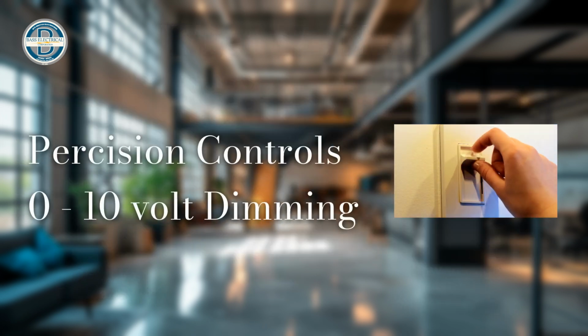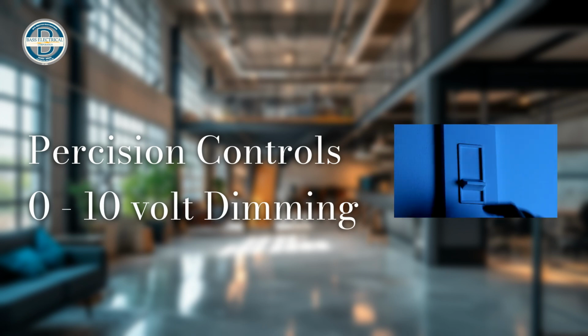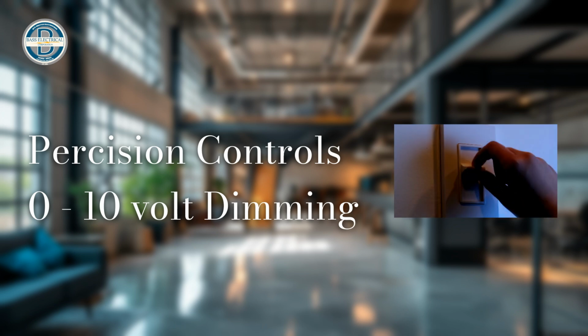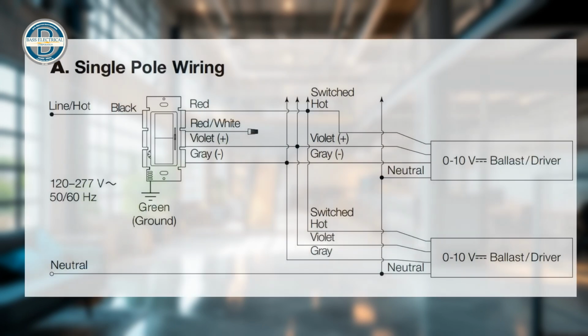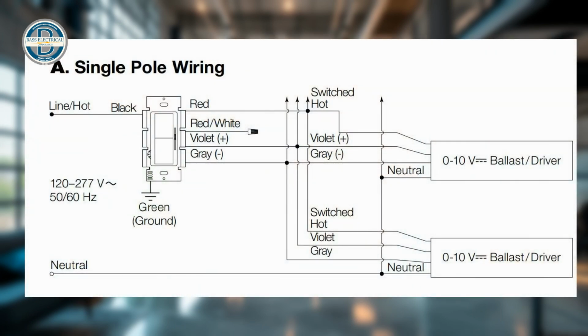Understanding drivers and dimming systems is crucial for effective lighting control. By selecting the right components and wiring them correctly, you can achieve precise control over your lighting environment. This wiring diagram illustrates a 0 to 10 volt single pole switch setup used to control a light fixture.